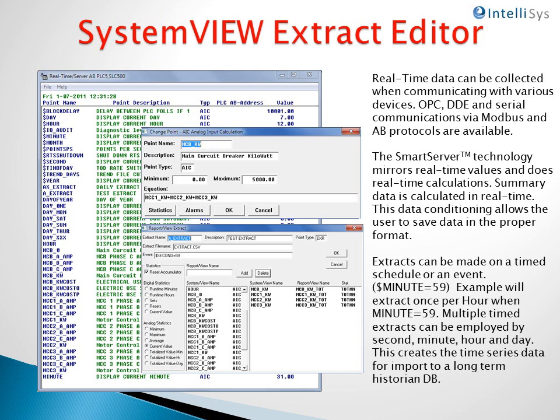Also part of the real-time server is the extract editor. The extract editor in this particular case is shown extracting 4 different points to the historian, if you will. In this case, we're actually extracting a calculated value, which was the sum of kilowatts from MCC1, MCC2, and MCC3, so possibly the main circuit breaker total kilowatts.